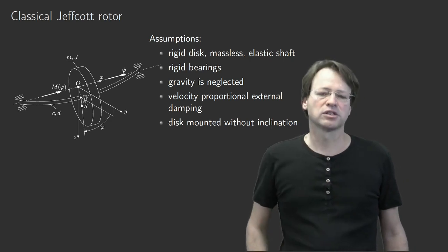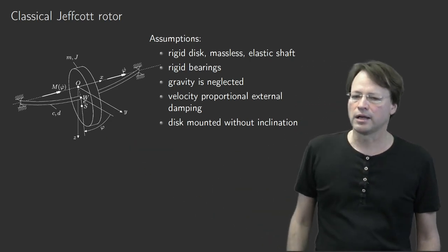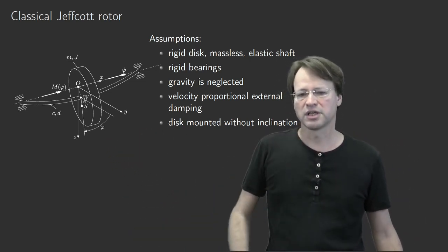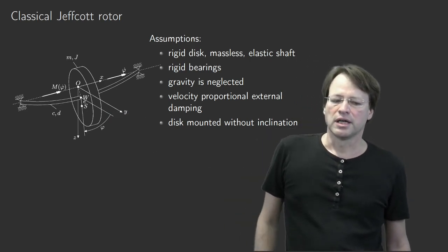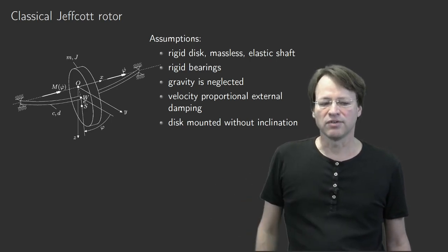So torsional vibrations are very important for drivetrains, but for these rotor dynamic system with one rigid disc and a very flexible shaft, usually torsional vibrations are of less importance than these bending vibrations.